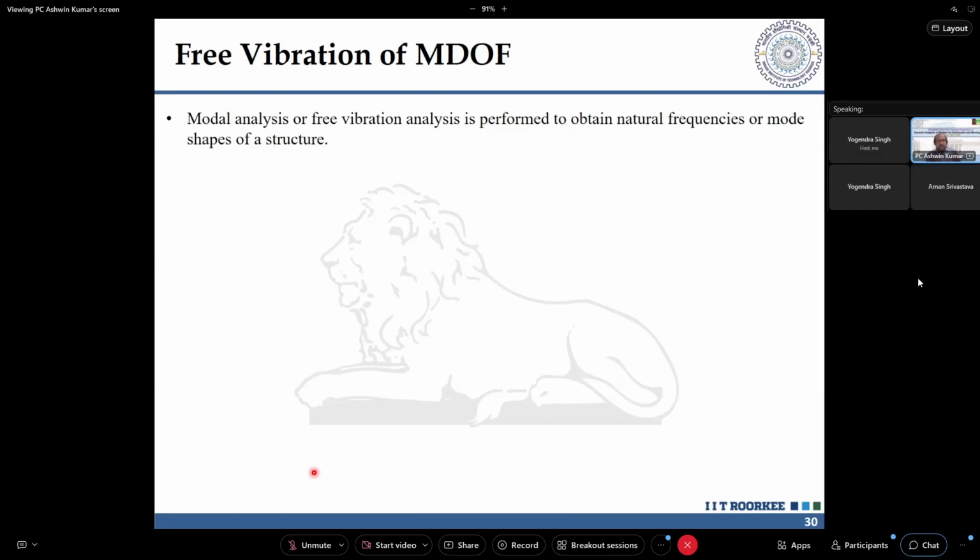Whereas with respect to the second natural frequency of that system, what you saw is that the upper mass is moving right, the middle mass is almost staying the same, and the bottommost is moving towards the left. But whatever happened at that frequency, it was giving the peak response. Like in the single degree of freedom system, when we saw the shake table example, the most flexible system is moving rapidly while the other two are quiet.